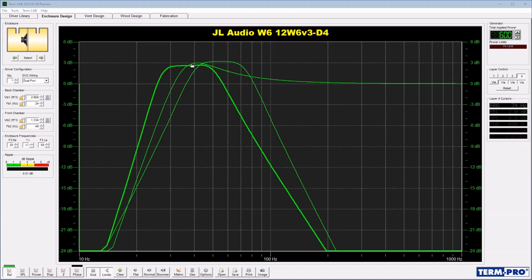There's also going to be an issue of personal preference. These enclosures have a distinct sound. I personally prefer the sound of a vented box to one of a bandpass box, but that's a personal preference. If you're talking to your customer and they're playing rap and they like this artist and the bass tones are the same note, then a bandpass enclosure would probably be real suitable. I'm going to do away with the 6th order box because it's a lot bigger.